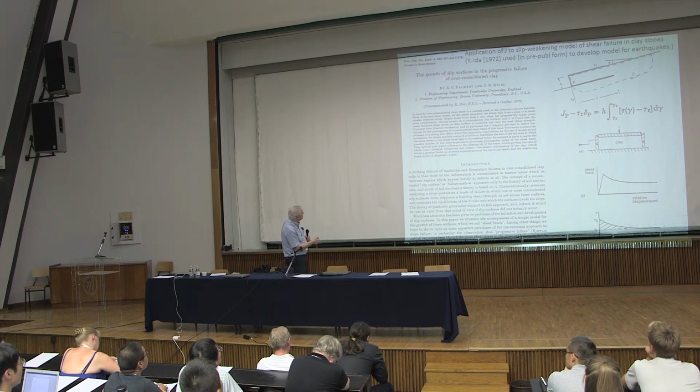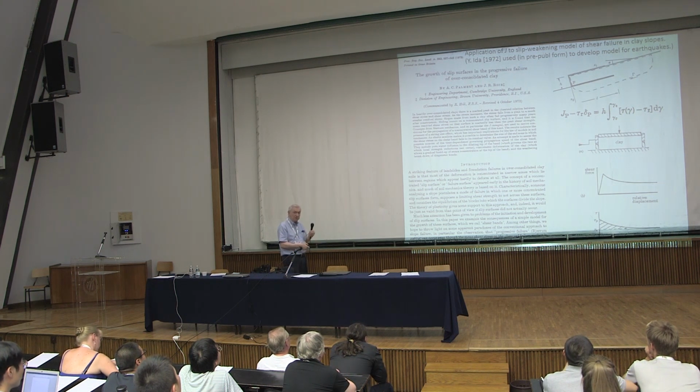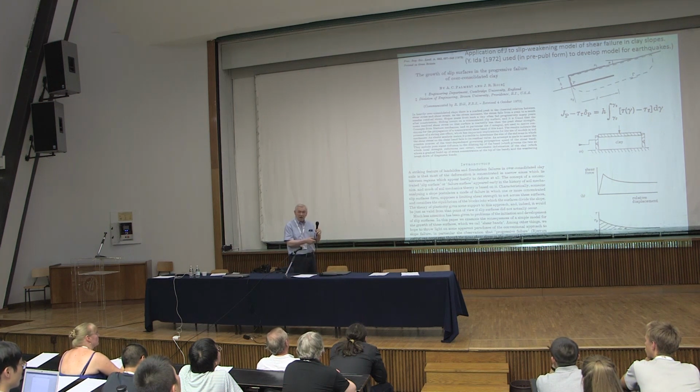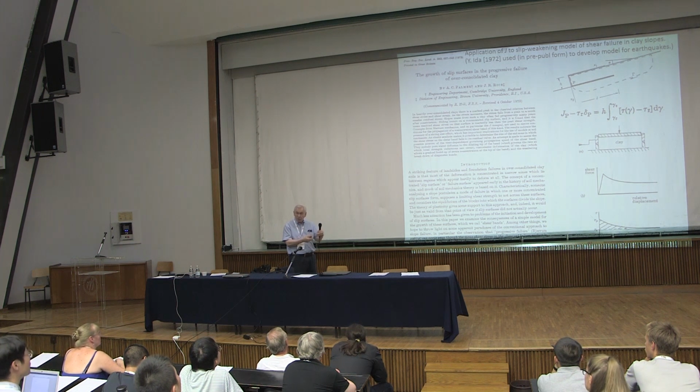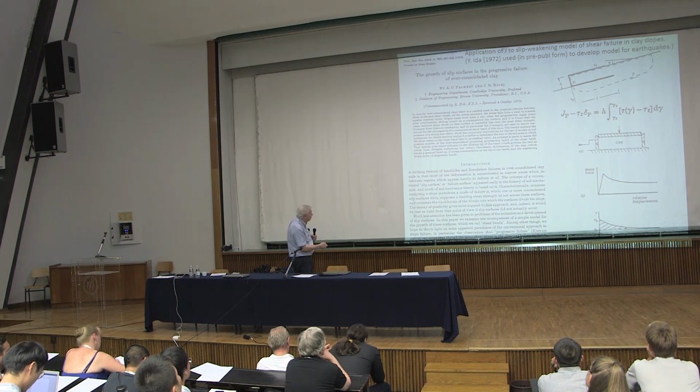But we got interested in how slip surfaces develop in clay slopes, especially heavily over-consolidated clay. That means it's stuff that has been smashed down and lost a lot of its water content, but when it deforms, tends then to dilate during shear and suck in any water that's available nearby in the sediments. And this was the application that we made there.